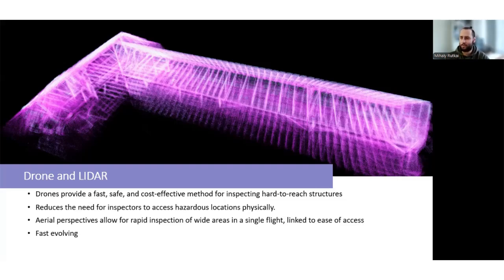Instead of a confined spaces rescue team, access, and engineers, the inspections can be done with a drone operator and an engineer, which these days can be one and the same. With their cameras and LiDAR, these drones can cover large areas of a structure in immense detail that can either be reviewed as videos or even stitched together in full 3D maps where even cracks can be investigated. I've seen a couple of jobs where 3D drone mapping was used on a large structure where engineers had to count the amount of broken tiles in a roof section and actually guide the repair and maintenance plans without ever having to set foot on the roof.